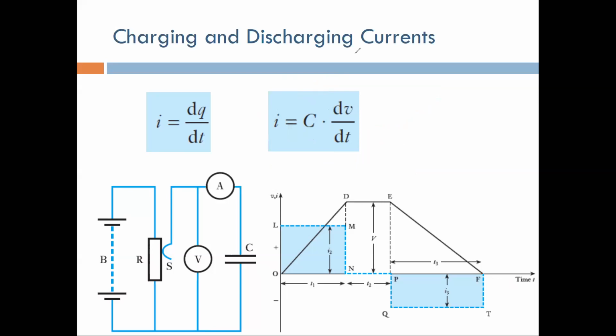So doctor, can you say the current will be 0 when the capacitor is fully charged? No, actually, it's going to keep charging infinitely. Ideally, if you have a constant current going all the time, it's going to keep charging without any limits. There is no such thing as fully charged for a capacitor. It's not a battery. If you have current going through the capacitance, it's going to keep charging until infinity if the current keeps going at the same rate.